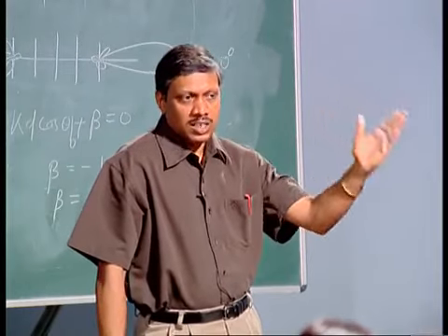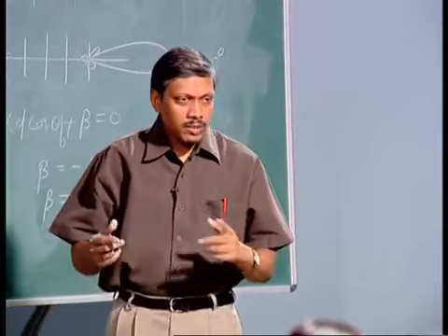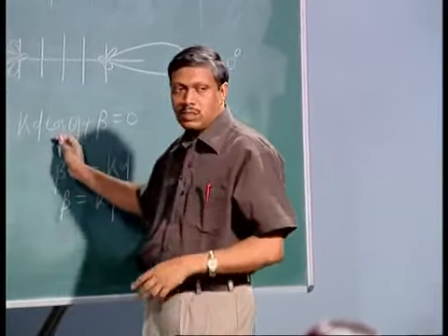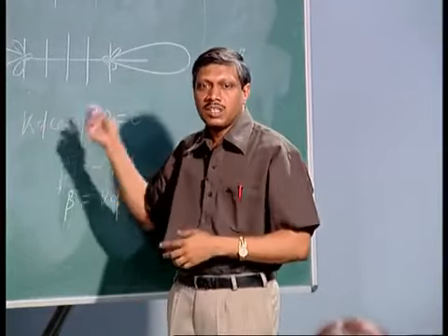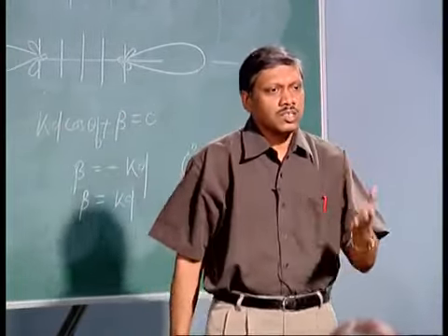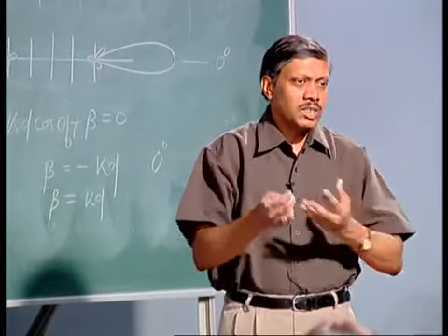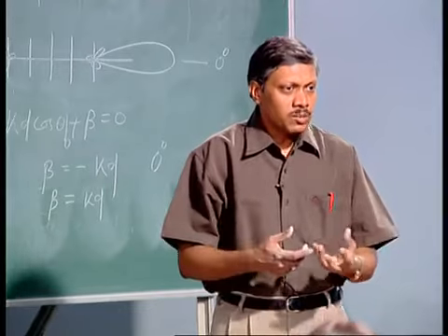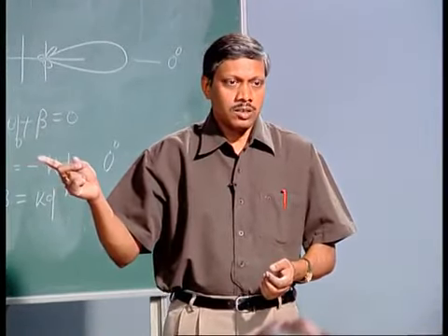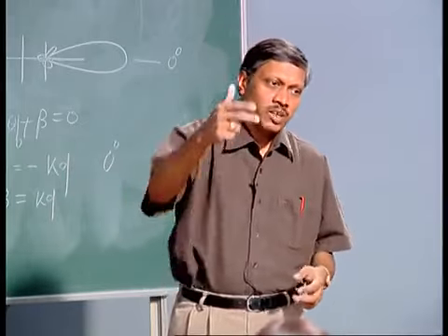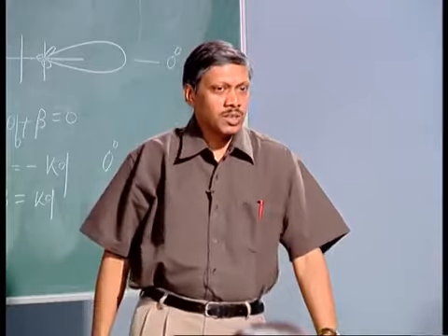So, it is not along the 90 degree, not along the 180 degree. Why? Because already you have seen two conditions. This beta, when it is 0, it is 90 degree. When this beta is equal to minus kd, it is 0 degree. When this beta is plus kd, it is your 180 degree. That means beta, which is within your control, is a parameter which helps you shift the lobe. So, if this beta is taken different values, obviously it will give you different shifting.